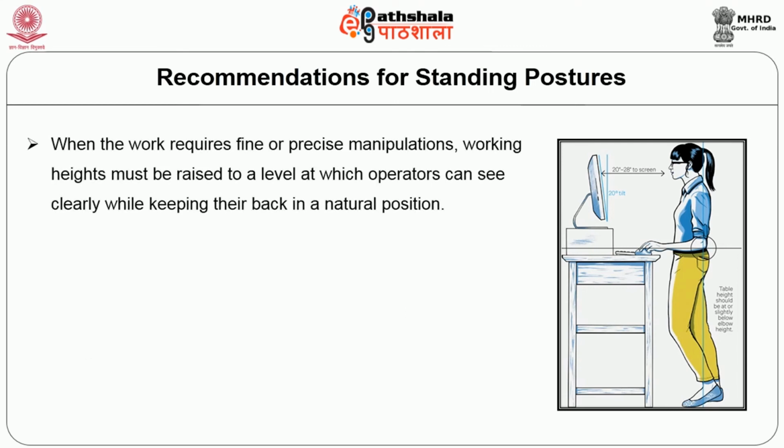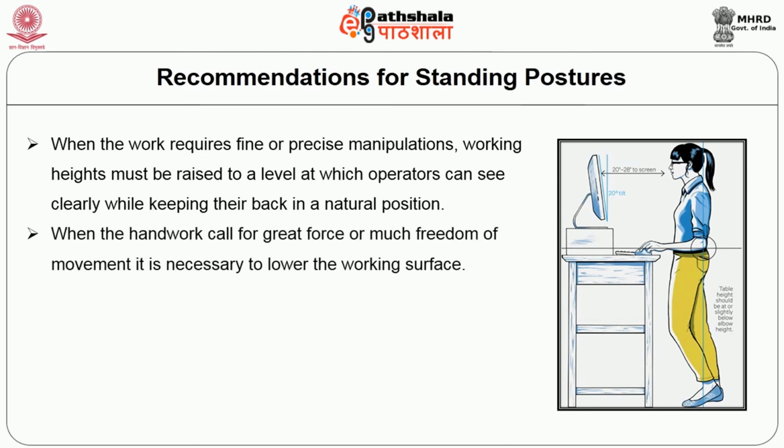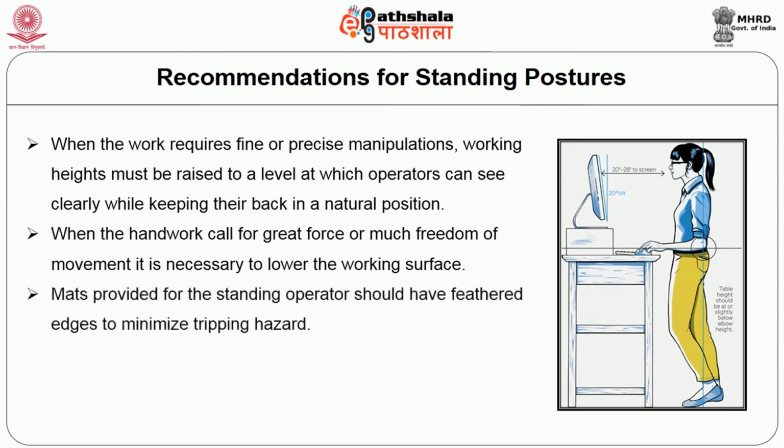When the work requires fine or precise manipulation, working height must be raised to a level at which the operators can clearly see while keeping their back in a natural position. When the handwork calls for greater force or much freedom of movement, it is necessary to lower the working surface. A mat should be provided for the standing operator, and it should have feathered edges to minimize the tripping hazard.